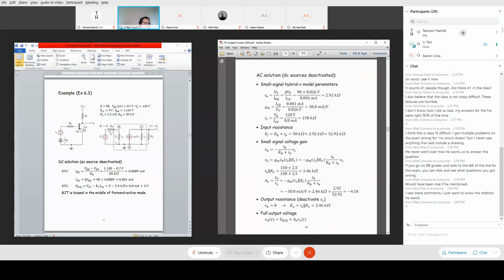And then the resistance. This is a PNP transistor, so VEB is important. The positive side of VEB, called V pi, is at the emitter, and the negative side of this voltage V pi is at the base. So V pi has plus-minus polarities.